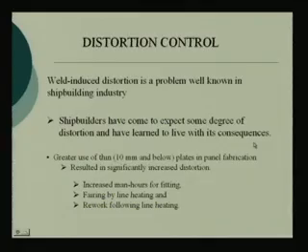What are the consequences? One of the consequences is rework, fairing, if at all. The major difficulty is alignment, because one panel has distorted, so the other panel matching will be difficult. So, a lot of rework is needed such that you do that alignment.